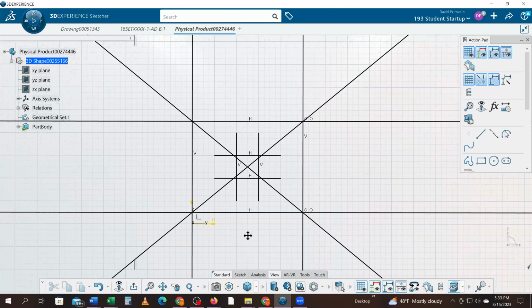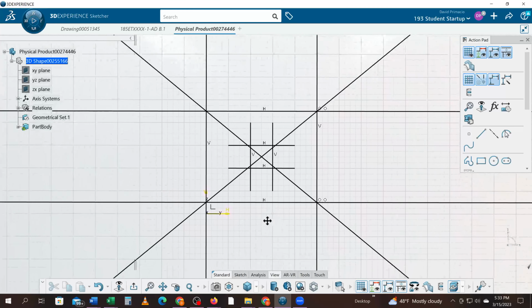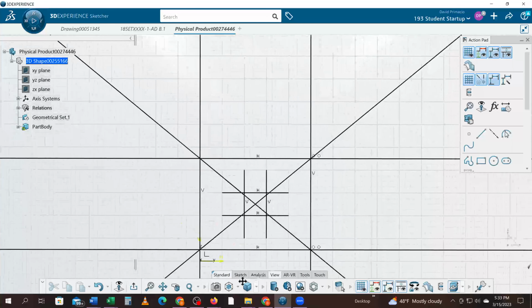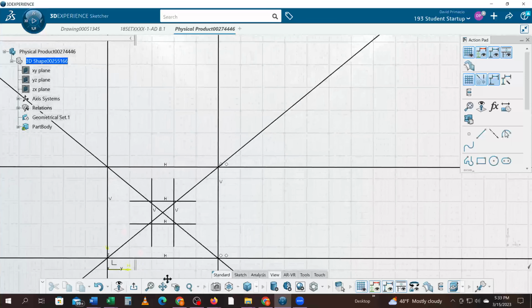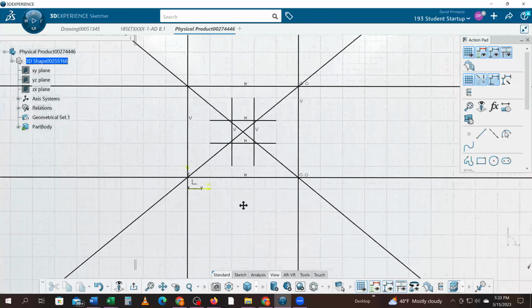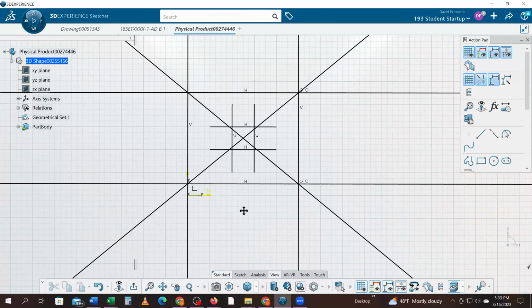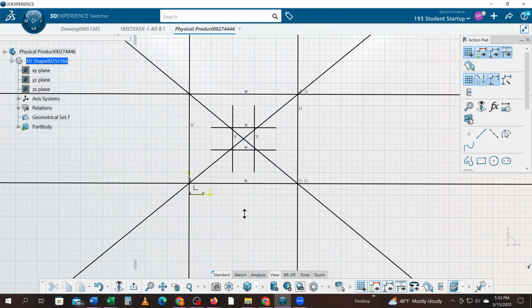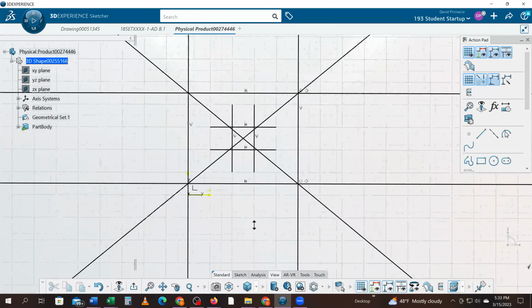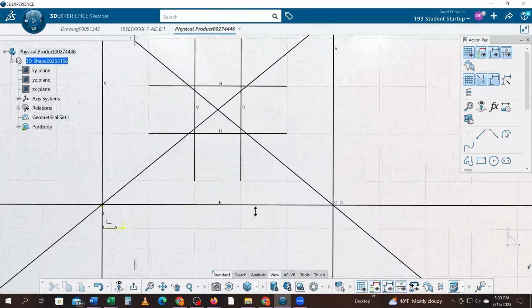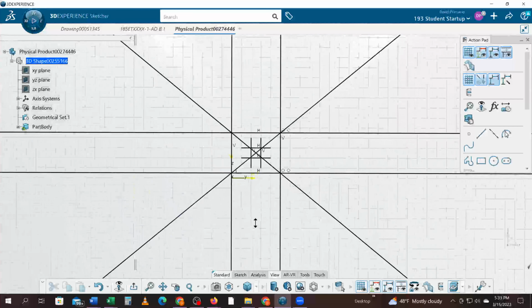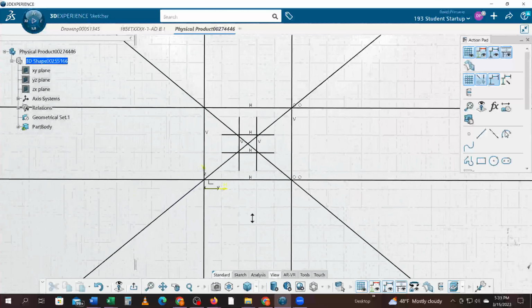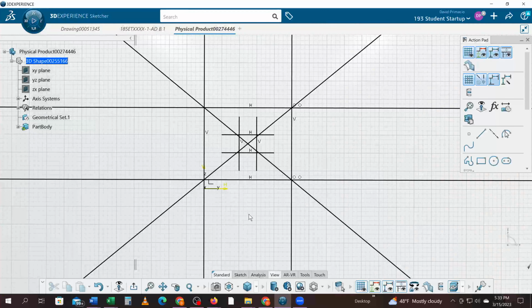While leaving the middle button down, you'll see my cursor has a pan. It matches the view pan right here. If I leave that button down in the middle and left click or right click, just tap it, but leaving the middle button down the whole time, it'll switch to an up and down arrow, which will allow me to zoom in and out as well. If I let go of the button, it stops, and then it just lets me draw lines and such.